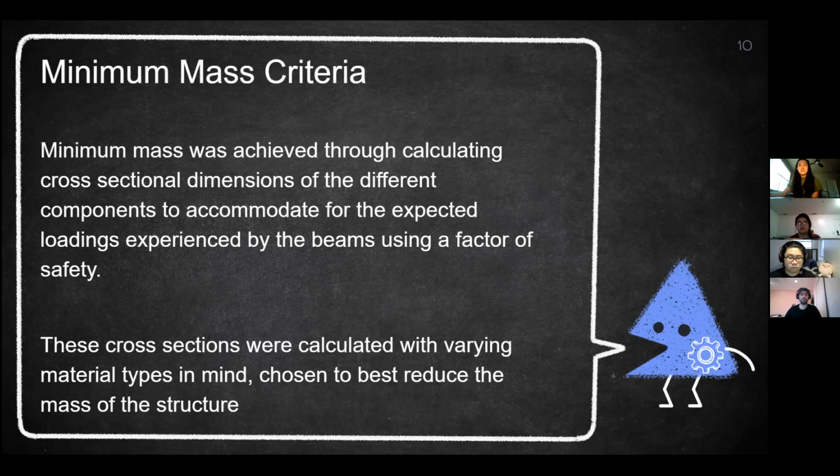We were initially going to use 304 stainless steel for the rolling pin due to its incredibly high elastic modulus, but we ended up instead choosing 2024 aluminum for our rolling pin for its high compression and tensile strength capabilities as a metal and its resistance to bending and deflection, while being more lightweight than steel. 2024 aluminum was a better fit for our purposes as it provided the required strength while reducing the mass of our structure as much as possible.